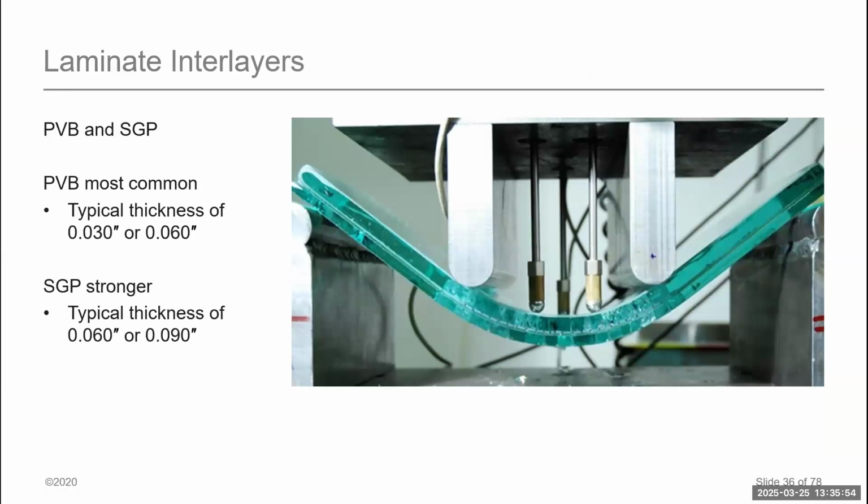Now, one of the things that I need to strongly caution you about, as somebody who has been involved in the design and engineering of hundreds of guardrail projects, is that PVB and EVA will not calc out at a typical 42-inch high guardrail. They will make it at about 36 inches at a 0.06 for a typical PVB. Now, there is structural PVB in the market that can get there, but a typical PVB or EVA will not work for a typical 42-inch guardrail.